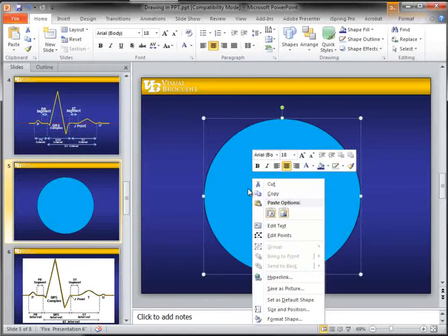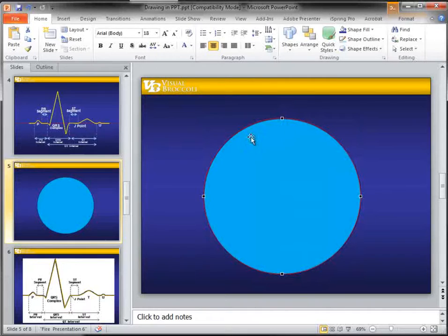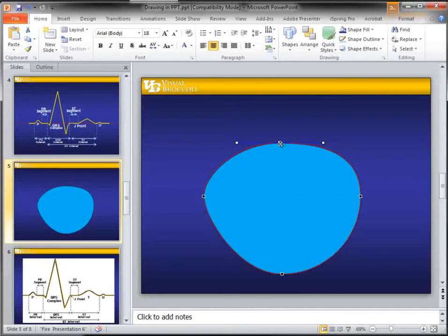Okay, now that being said, let's show you some basic ways we can manipulate this circle. If I right-click on this, I'm going to edit points. And you'll notice now I have 4 points because this is a circle, and I can move these points to anywhere I want. Let's bring this down just a little bit here, and that's looking good. And I'm going to grab one of these handles. The best way to describe these handles is Bezier curves, and these are Bezier handles. If I move the handle, you notice how the line follows the handle.